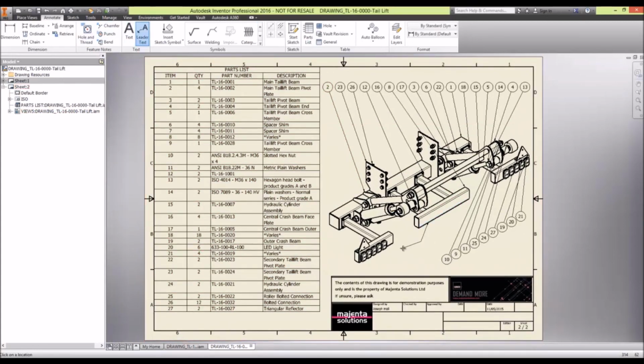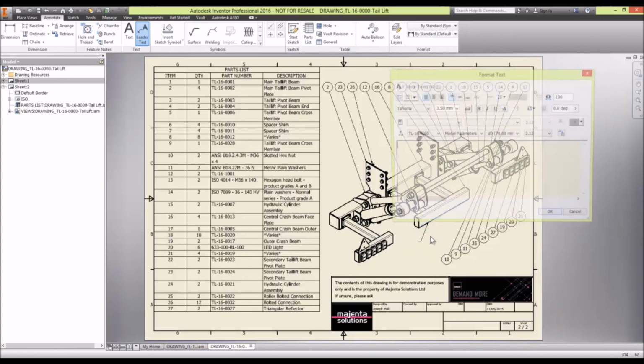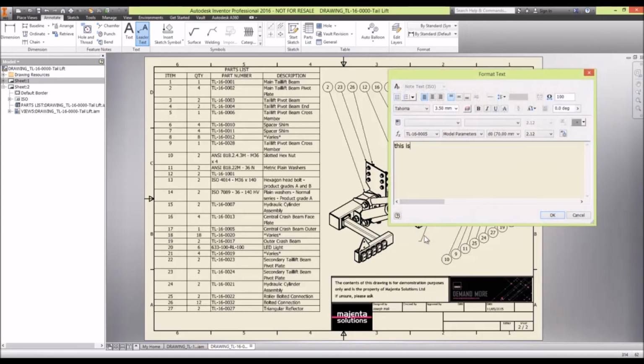So as far as creating drawings is concerned, we have the ability now, if I was to put some additional leader text on here, so maybe create and continue. You can see there's the preview that's appearing on screen at the moment. So let's put something like Magenta Academy Live videos. So you can see it's dynamically giving me that text as I'm typing it in the box. We've got the addition of some symbols in here as well if I need to.